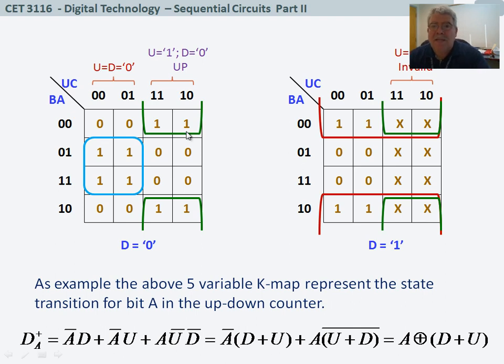Imagine that we overlap these two K-maps, one over the other, and then you can also find that these four here are adjacent to these four because they're exactly on the same set of variables. The only difference is D. In this case, D changes 0, 1, and this is the variable that does not matter. Aside from that, there's nothing else common, and then we can use particular with D1 here.